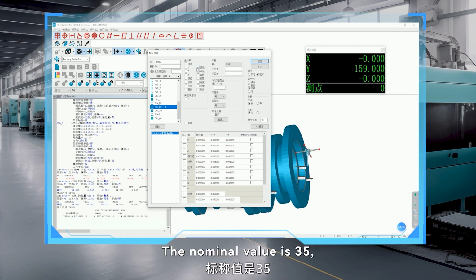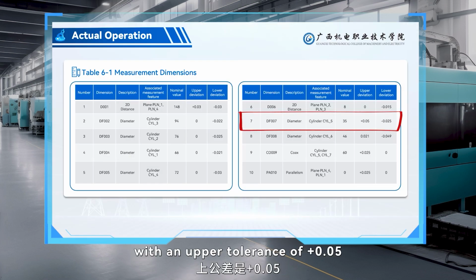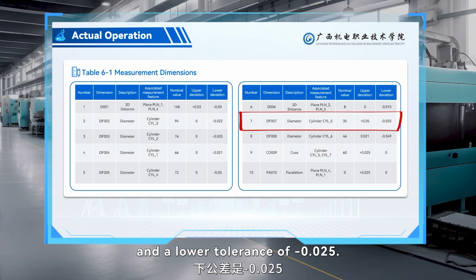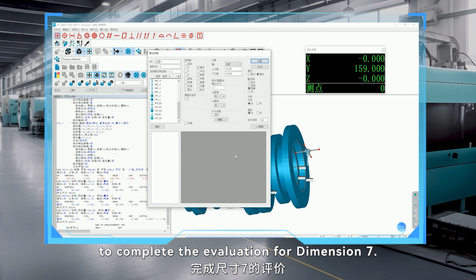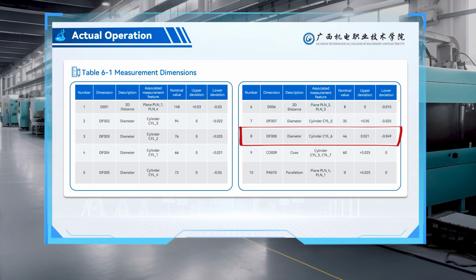The nominal value is 35, with an upper tolerance of plus 0.05 and a lower tolerance of minus 0.025. Click Create to complete the evaluation for dimension 7.